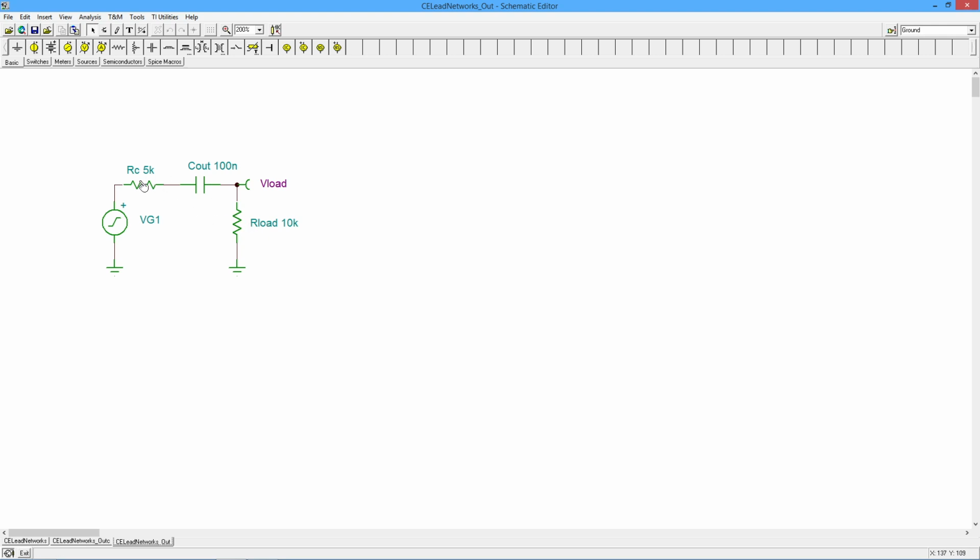You could think of this as loaded versus unloaded voltage gain, basically. But nonetheless, it's only until the frequency gets low enough that X sub C starts getting into the K-ohm range that we start seeing appreciable loss. So where does that occur? Well, it occurs where X sub C and R are the same size, the effective R for the whole thing. Well, what is the effective R for the whole thing? Well, we would simply do a Theveninization. We would find what's the resistance, the Thevenin resistance that drives C out.